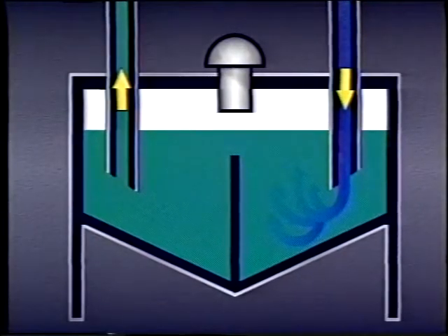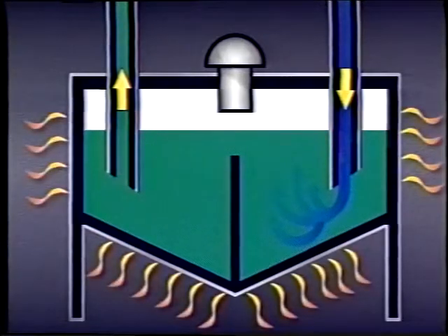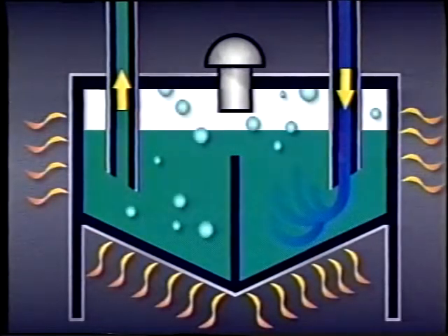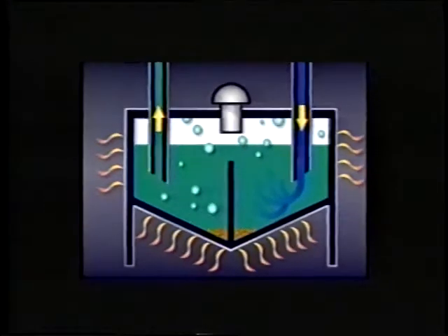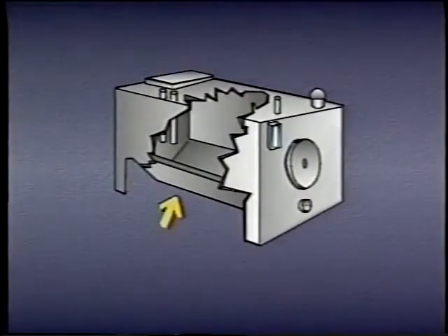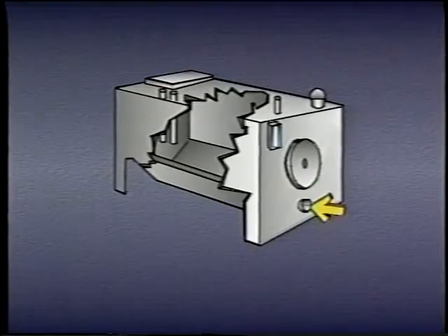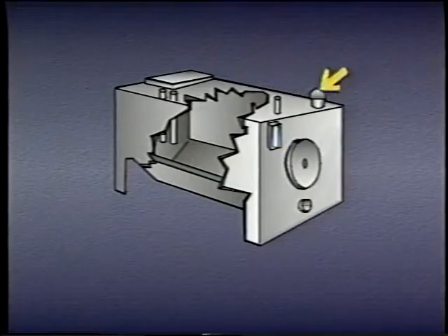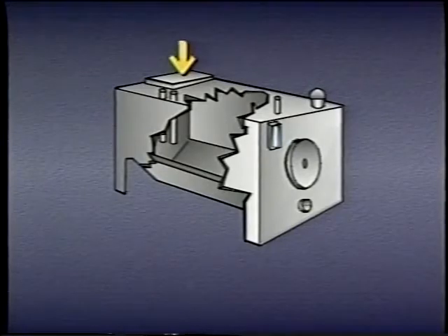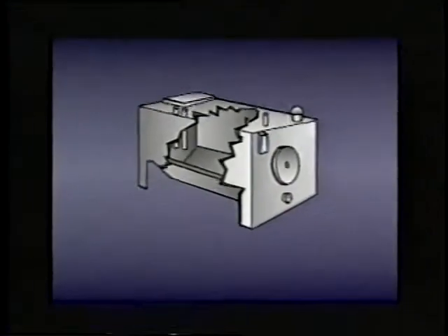The large steel sides absorb heat, cooling the fluid. At the same time, entrained air escapes and a lot of contamination settles out. The reservoir's dished bottom collects the dirt, and an end cover permits occasional cleanout. A drain allows sampling of the fluid. A gauge indicates the fluid level. A filler cap includes a built-in breather to let air escape. A sturdy plate provides a place for mounting the pump and motor.